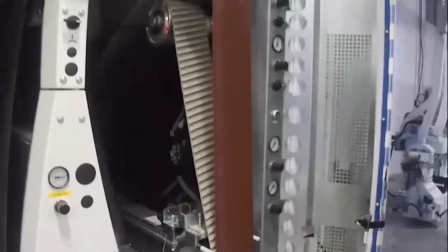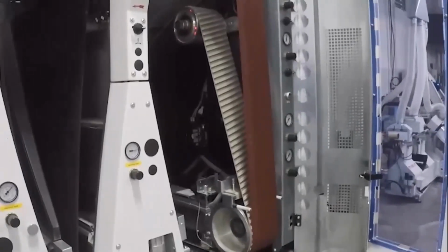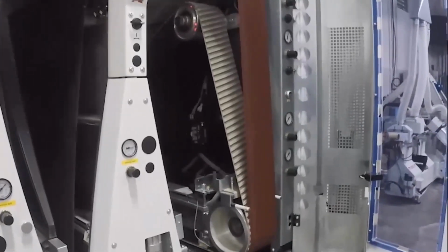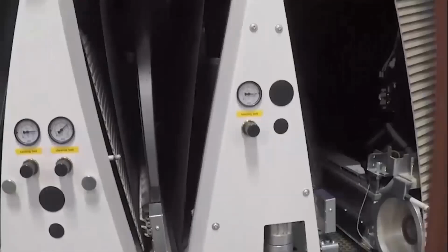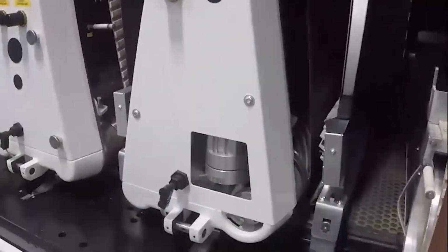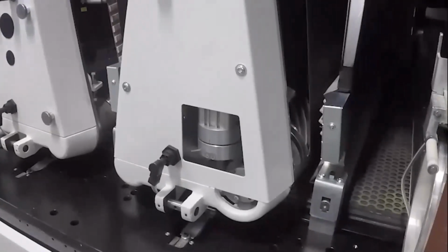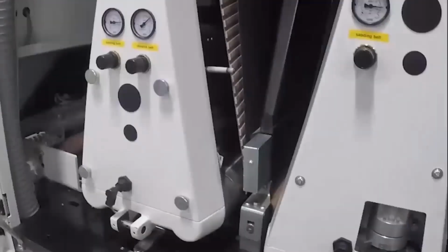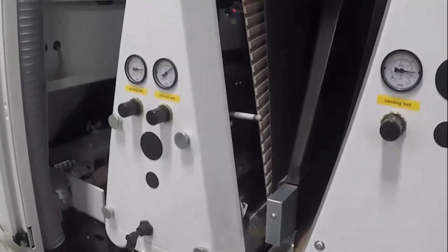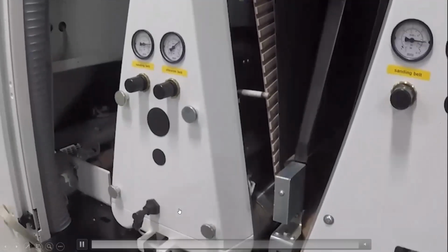So here, looking inside the machine, you can see what the cross belt looks like. We have a chevron belt on that cross belt to help keep it running cool and get rid of the dust. You can see the grit compensation there on the combi, along with the helically grooved steel drum for some calibration capability. And again, the last head, we have a chevron belt, much similar to what Addison was showing, but in this case, we have a magnetic pad inside.